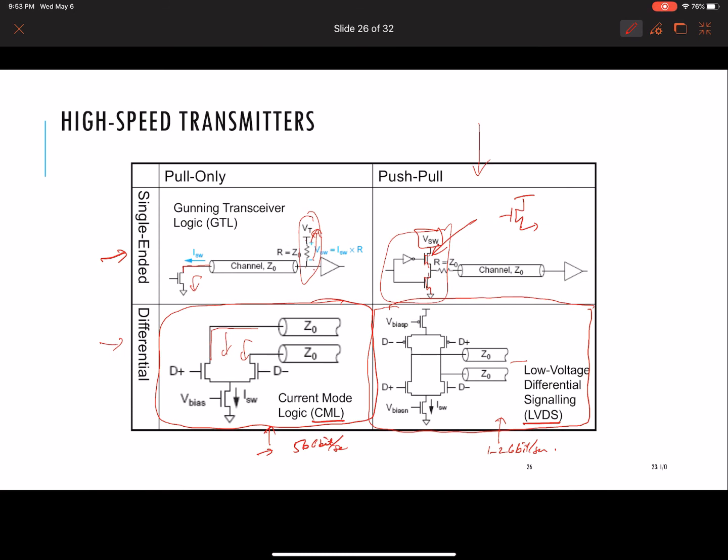But anyway, we're not going to get to those. Just leave it that there are a few different options for transmission lines. And I really do see all these different ones all the time. Certainly CML, LVDS, and stuff like this, more like DDR memory interfaces, etc. There's really not a standard, I would say, where all the transmission line drivers and receivers work the same way. So you'd better make sure the receiver you're choosing is appropriate for the driver you've got, and the same with the termination, that it's appropriate for the transmission line you're using and the driver that's driving you.